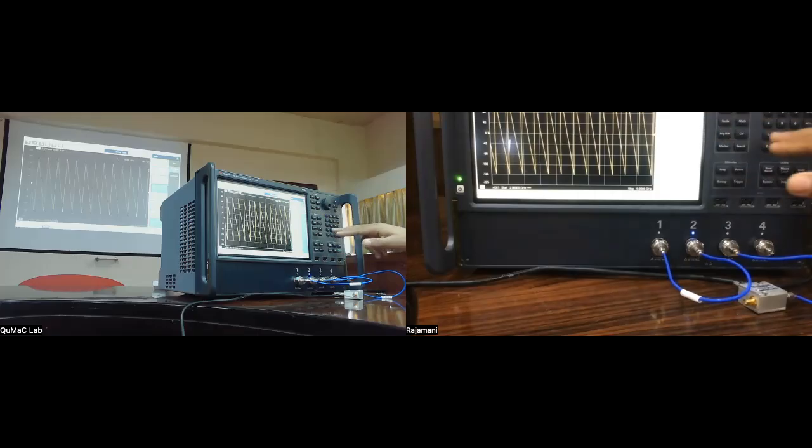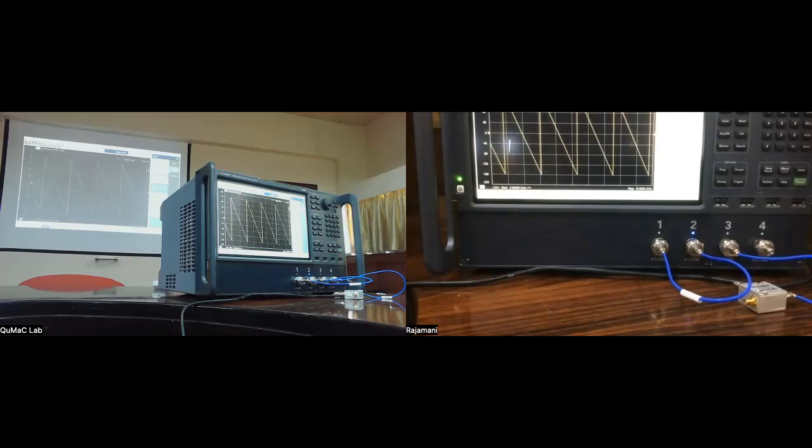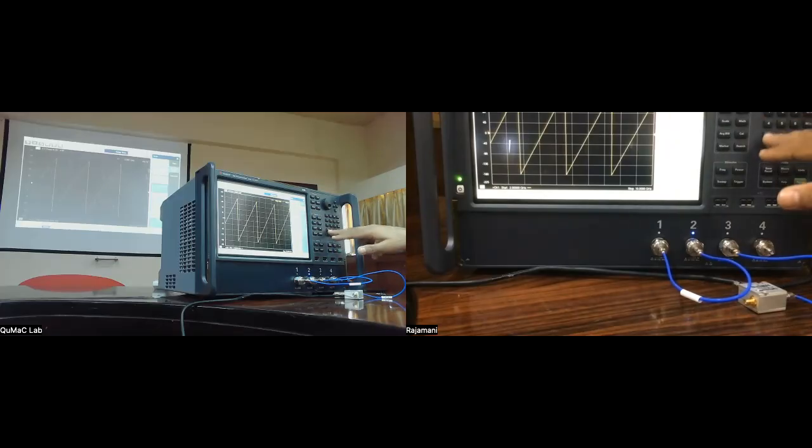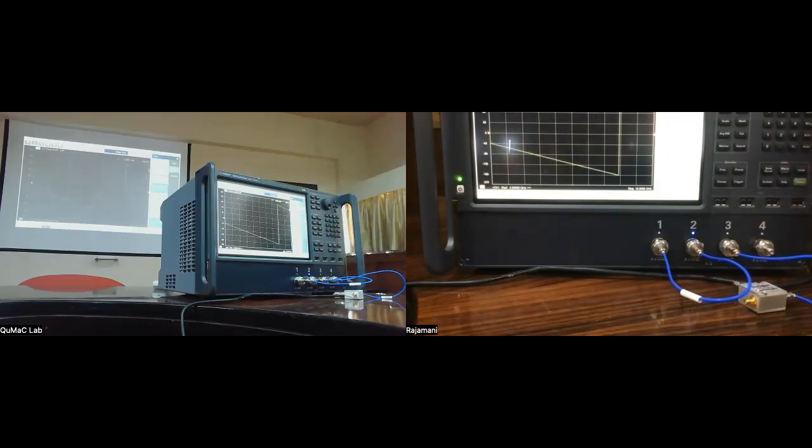So you go to the delay time and you enter a value of, say, 1 nanosecond. So it has now partially compensated it, because it's now sort of introduced a negative delay internally, just as a pure calculation thing, right? And so this is not enough. So I need to go a little bit higher, but this is too high now. It has overcompensated. So now you see the phase is going in the opposite direction. So I have to go somewhere in between these two numbers.